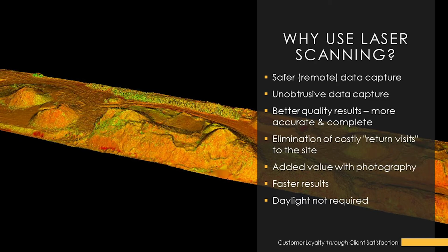Well, cost is at the basis of so many things nowadays. So you want something done rapidly, quicker, faster, and safer. So the beauty of the scanning is, I always use the old analogy where back in the day, if a measurement scientist, a surveyor, was to go and gather information, it'd be items A through D, and those items would be gathered in the field. And then if E through Z was required, that would require a further mobilization. But with laser scanning, you're getting A through Z anyway at the time you're scanning, because everything that's within view of the scanner is gathered.